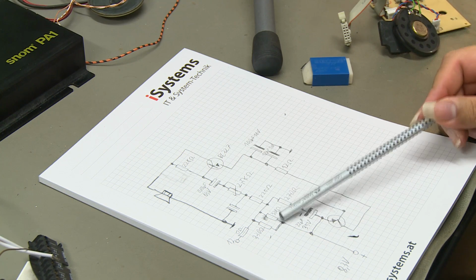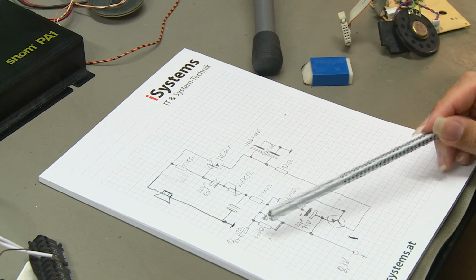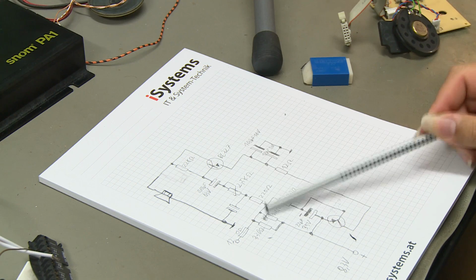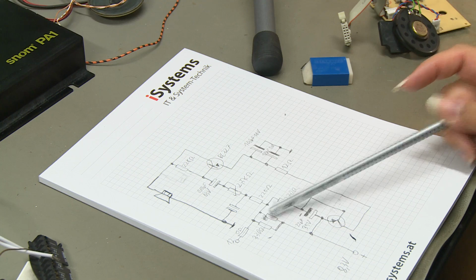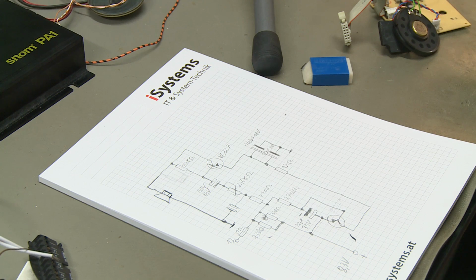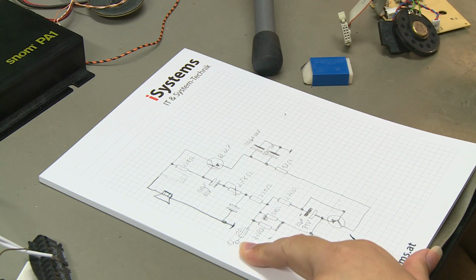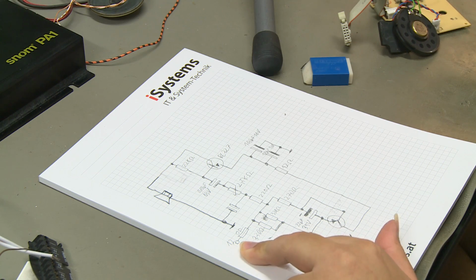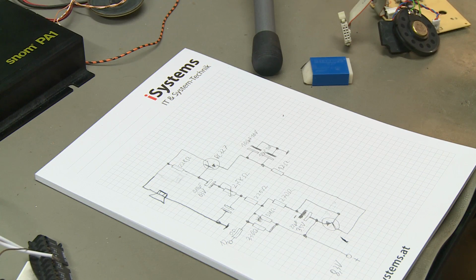So this 8.3 volts goes through resistors, which are actually 165 ohms, because there are two 330 ohm resistors in parallel, and through this resistor it's directly hooked up to the input, and there is no cap or anything isolating it from DC, which already is interesting.